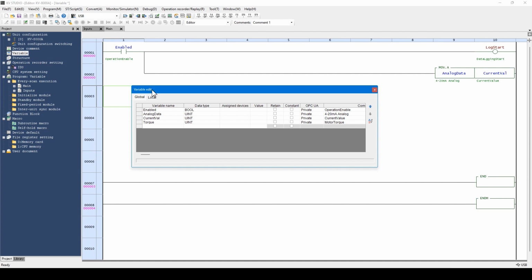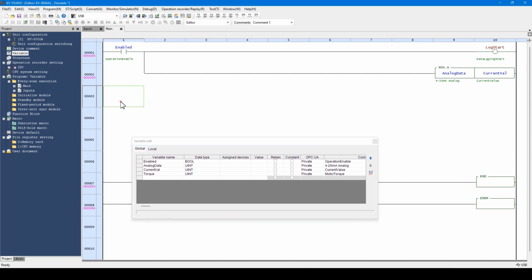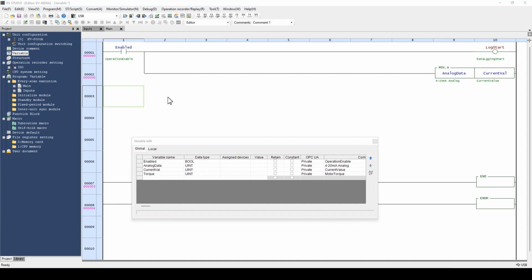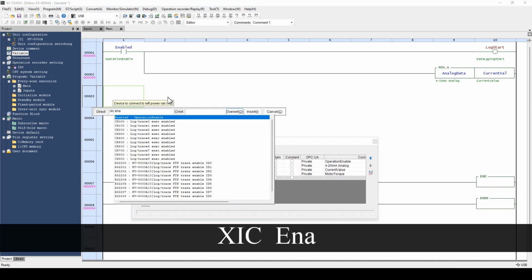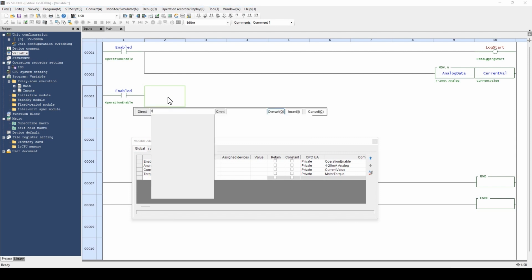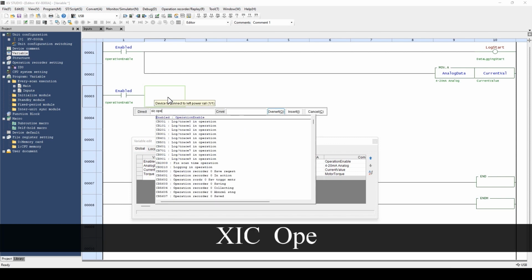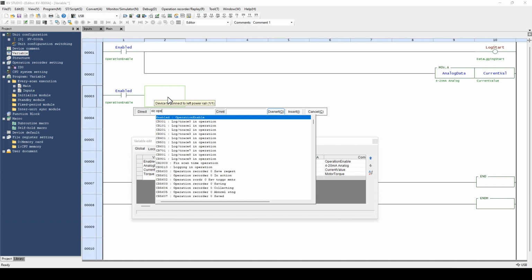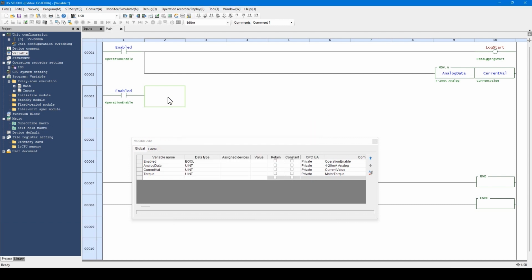Not only improving the readability, but a list of variable candidates is displayed when a part of variable name is entered in KV Studio. Then, pressing the Enter key automatically inputs the entire variable name. This function is also available for variable comments. As you can see, entering a part of input variable comment displays the candidates. Setting comments to variables reduces the man-hours for programming.